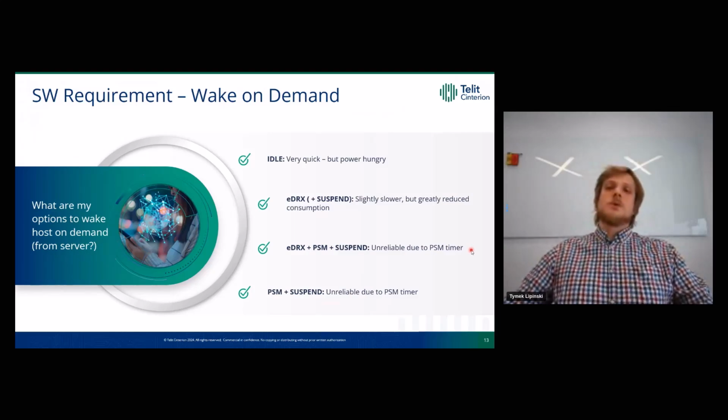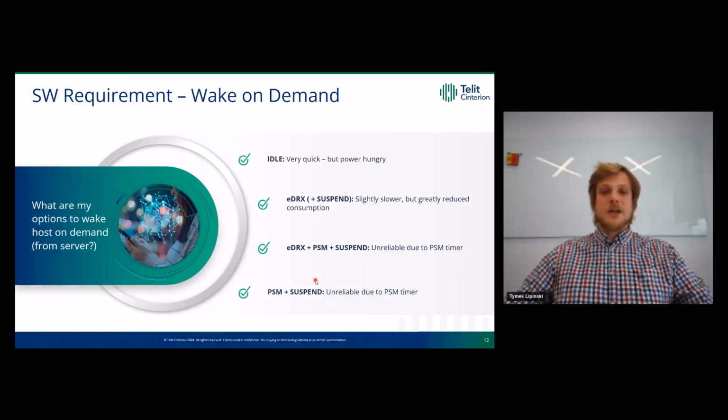So this shows a problem with synchronization between the module, the device, and your server, because you are not able to inform the server about the PSM timer assigned from the network. You just go to sleep. And it also applies without the eDRX, just the PSM and Suspend option. It becomes unreliable due to PSM timer.